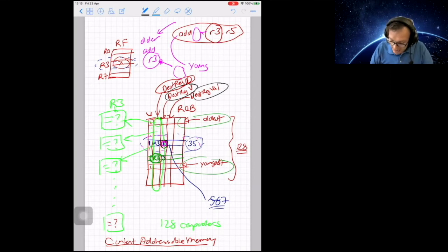Okay, so let me finish this by looking at the operation of the reorder buffer a little bit. Basically, once the oldest instruction finishes, you check for exceptions. Of course, there's some finite state machine, some control logic that checks every cycle the oldest pointer and the entry over here. If it finishes, what does that mean? It means that the entry is valid. Well, hopefully, if the oldest pointer is pointing to it, then it should be valid. Its destination register is valid, or if it's a store, its store address and store data are valid, etc. I'm not going to go into all of the details of different types of instructions over here.